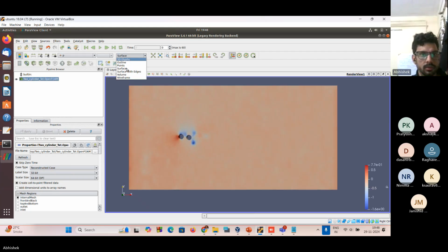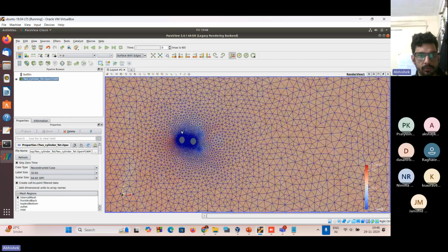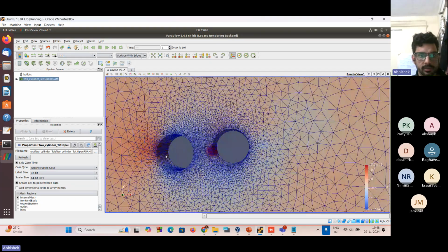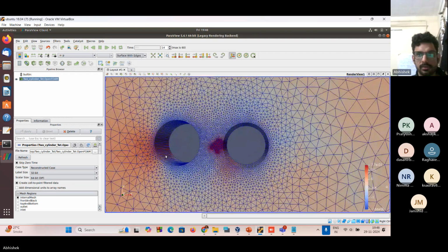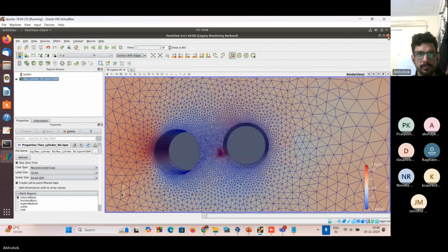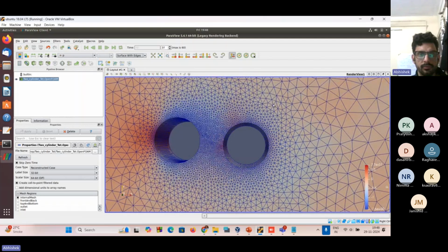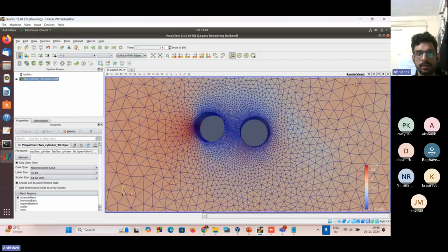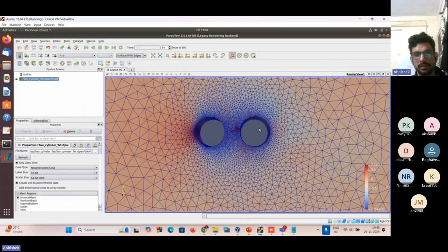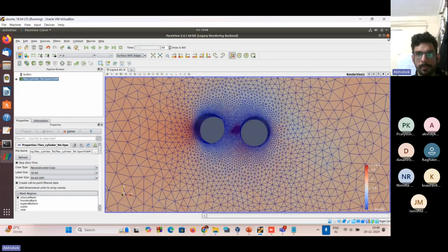See, you can see the vortex shedding happening from both cylinders and the upstream cylinder is moving. You can see the mesh deformation. All right. So when we have too many structures or a very complex structure, blockMesh is not suitable; tetrahedral meshes or other kinds of meshes are the way to go.